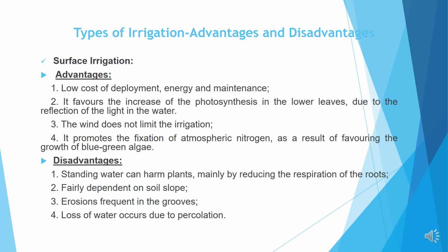The disadvantages are: firstly, standing water can harm plants mainly by reducing the respiration of the roots. Secondly, it is fairly dependent on soil slope. Thirdly, erosion is frequent in the furrows. And fourthly, loss of water occurs due to percolation.